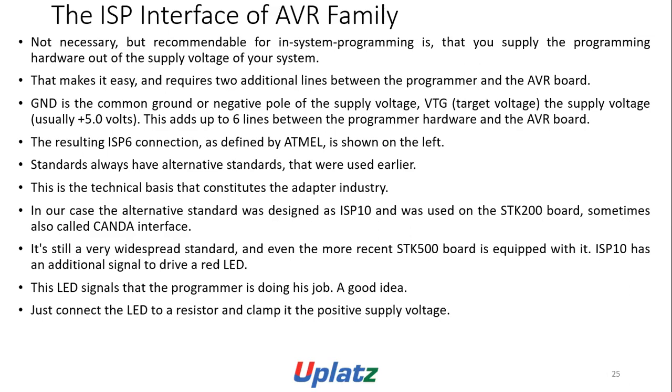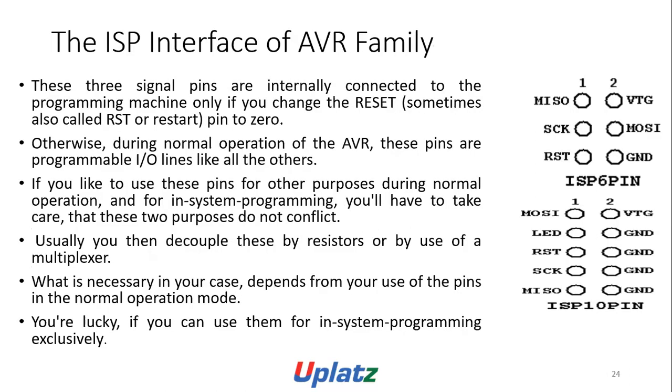It is still a very widespread standard, and even the more recent STK500 board is equipped with the ISP10 and an additional signal to drive an LED. This LED signals that a programmer is doing its job, a good idea. Just connect the LED to a resistor and clamp it to the positive supply voltage. The ISP6 pins and ISP10 pins are shown in this figure.